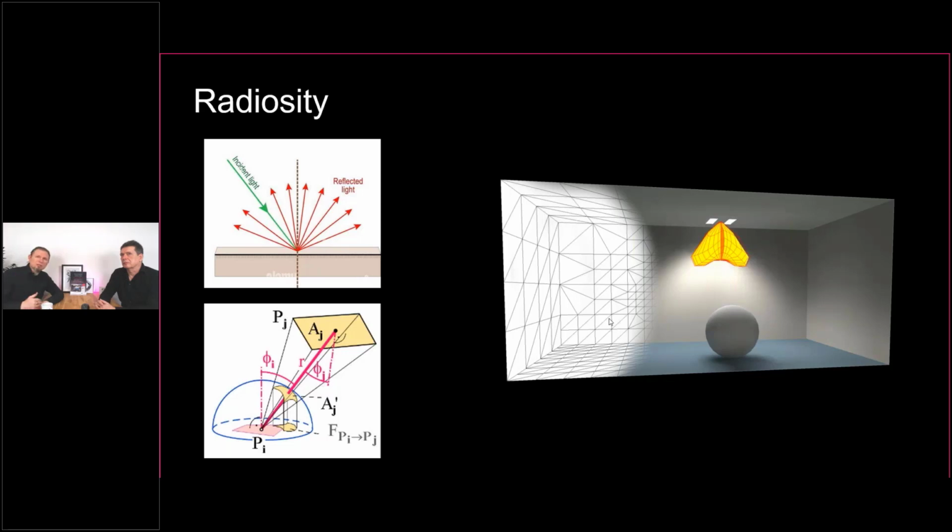But again, if you just hit the calculation button, you get a good average setting, like we have done here with this dynamic placement of tiles for the indirect part according to energy. This works well, but of course a higher accuracy is possible by setting. But again, it really depends on how accurately you can remodel the complete scenery. This is the biggest impact on the accuracy of the calculation results, and not the calculation method or roundings in the computer or something. It's really about how detailed you can get everything from outside.